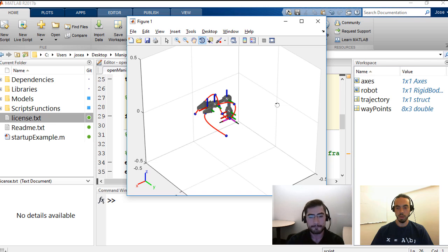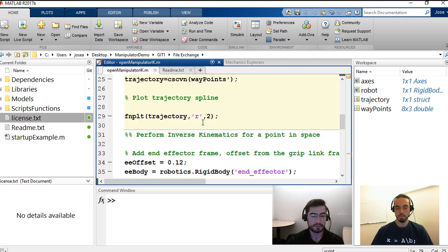Basically, what this Curve Fitting Toolbox function does is fit a curve between every set of 2 waypoints, and then we get to choose at which resolution, or how many points in between, we want to sample for our trajectory. Correct. So in the first part of the script, we're only plotting it using one of the plot functions within MATLAB. Later, when we start actually trying to follow the trajectory, we're going to be evaluating it at whichever points, discretizing it with however many points we want.